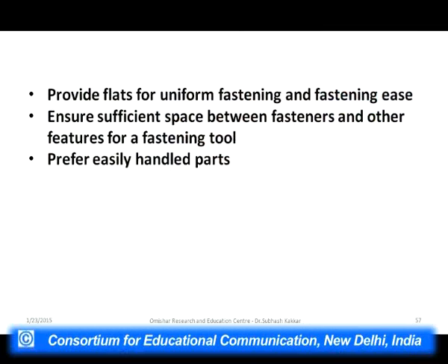Provide flats and uniform fastening for fastening ease. Ensure sufficient space between fasteners and other features for a fastening tool. Prefer easily handled parts.